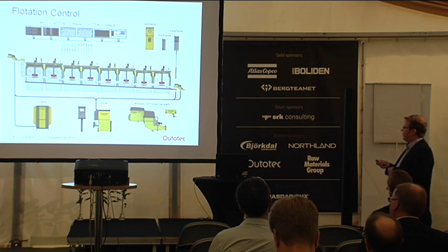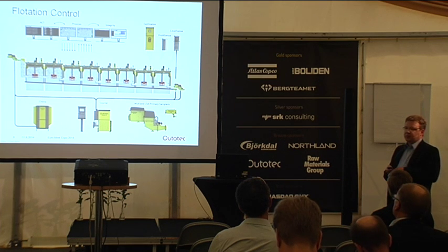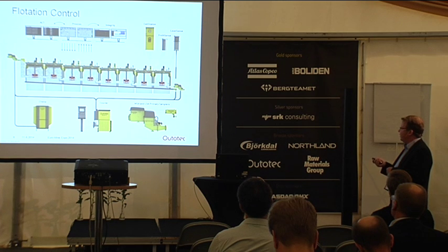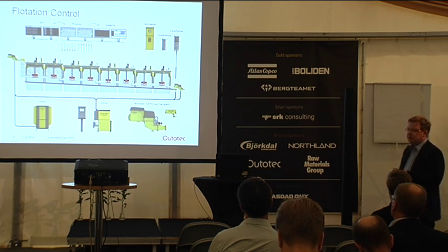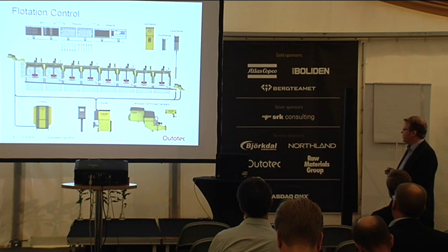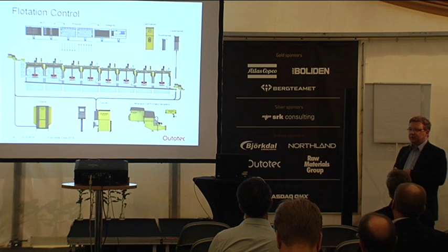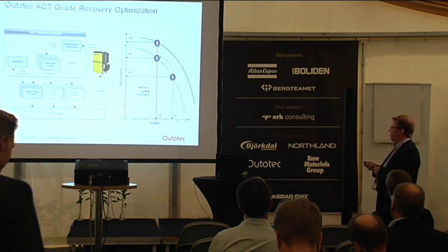Then a newer product for slurry level measurement called LevelSense improves the slurry level measurement and also allows some advanced options for froth characteristics estimation. FrothSense froth imagers measure the froth speed, bubble size, and color on top of the flotation cell, and CellStation is a unit controller for the level and air in the flotation.